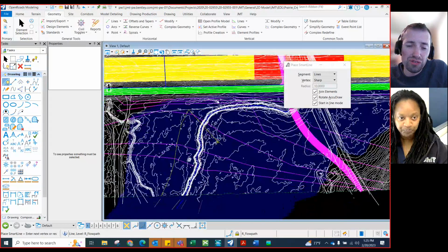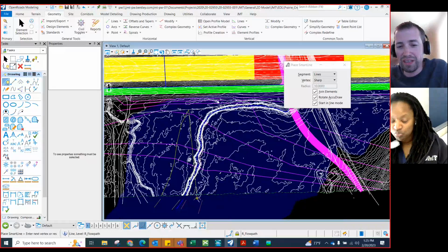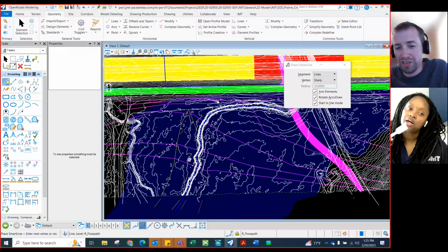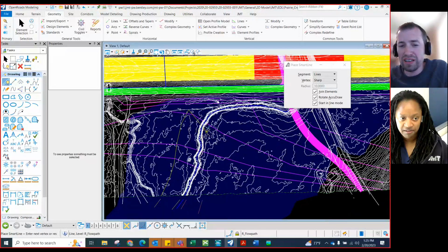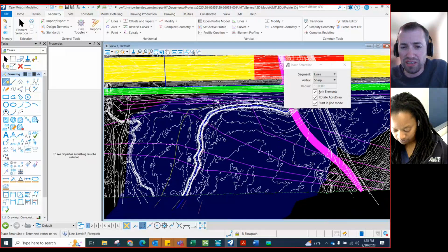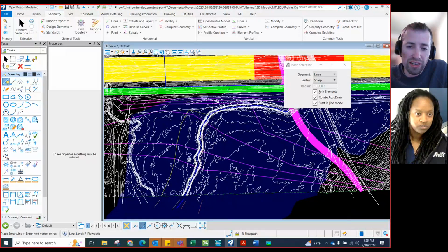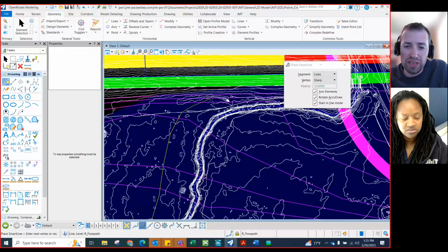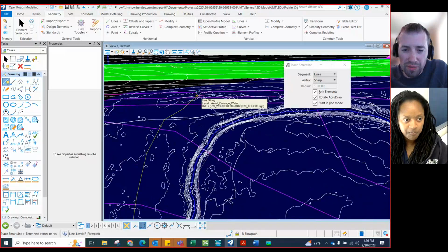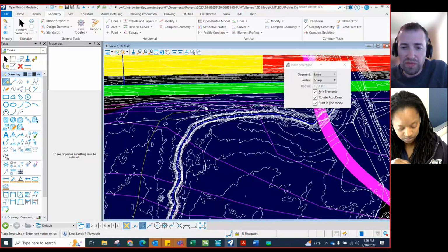One thing, so usually if you're building a model from scratch, these steps are done before you do a cross-section line. Since I'm taking someone else's model and verifying it, maybe making some tweaks, I already have some cross-section lines. One of the rules is I want to make sure the cross-section lines do not cross any of these lines we're drawing today, the channel, flow path, banks, more than once. So be careful that I'm not crossing it 3 times. That'll give you some errors when you try to run things.